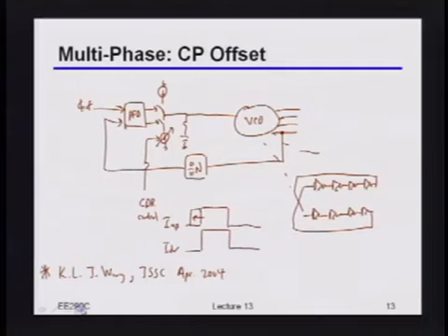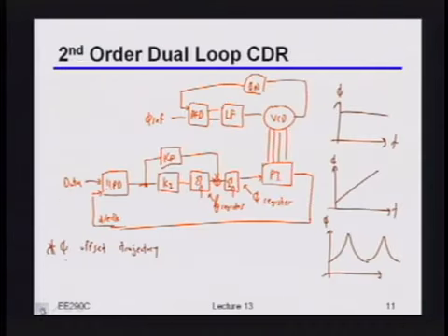It's not to say you can't do it, but it's definitely a lot more painful than, for example, with these phase interpolator kind of things, or in the phase interpolator, and we'll talk about that in more detail when we show exactly how that's built. But conceptually, in the phase interpolator, since you're just picking different phases, it's a lot easier to do that wrapping, right? Because you just pick a new phase that basically corresponds again to 0 degrees, okay?